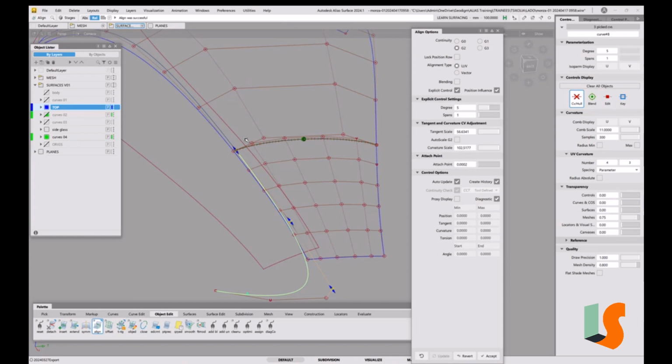Easily fixed, but you've got to spot it. If I just drag that in that direction, you can see it's now one arrow. So that means it's absolutely to the end of that. If you don't get that right, then you'll end up putting in surfaces which don't align, and you'll think, what the heck's going on? So it's one of those tiny little details that's well worth spotting.